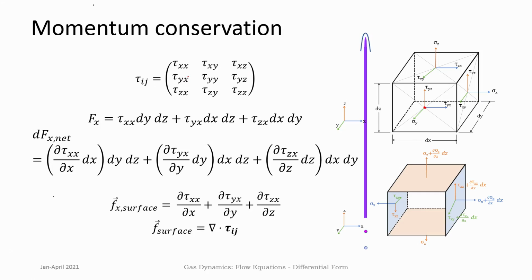So, if you take any particular point and have different surfaces, you have forces along different directions. Force divided by area is a stress. So, at a particular point you can have a state of stress, and stress is actually a tensor, because at every surface you can have forces in every direction. So, tau xx represents a force along x direction, F x, over an area whose normal is also along x direction. You can look at the coordinate system here and understand them.